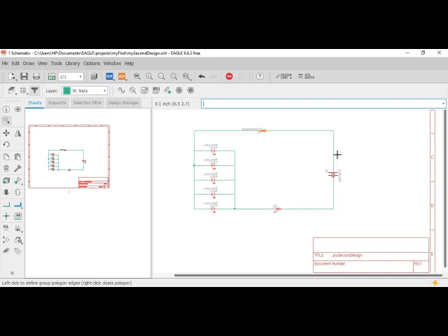Like what we did yesterday, we tried to make sure the current that flows from this battery is allowed to move in only one direction through the PN junction diode, and the voltage is being limited by this 10K resistor, so that the high voltage will not affect the LEDs.